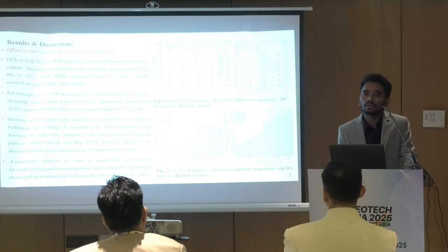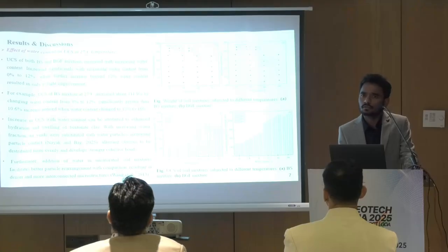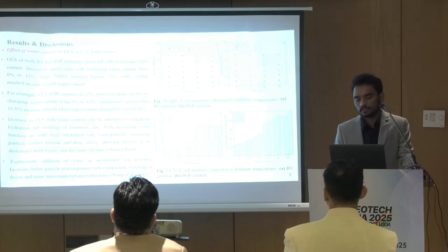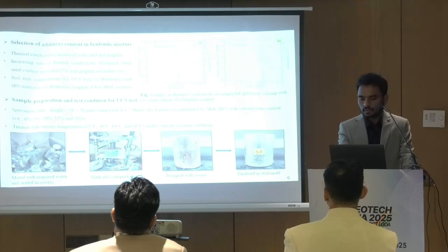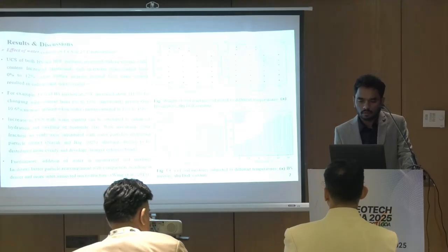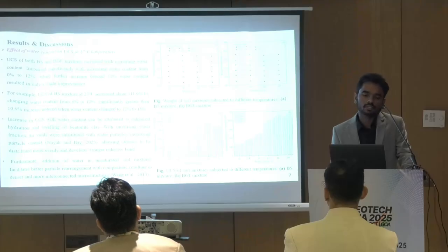Next, the results. The unconfined compressive strength test was conducted at different temperatures. The temperature was given by keeping these containers in a thermotank. The required temperatures were 27 degrees, just room temperature, and 40, 60, and 80.